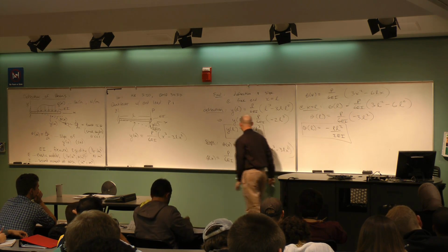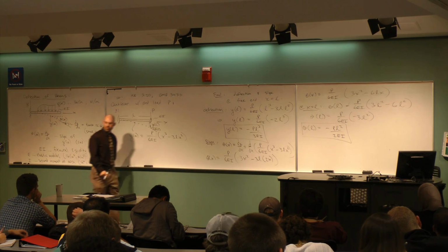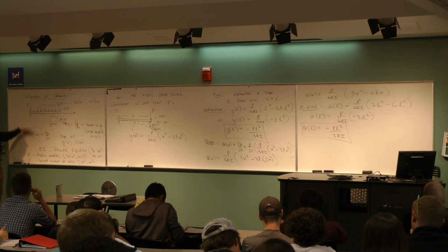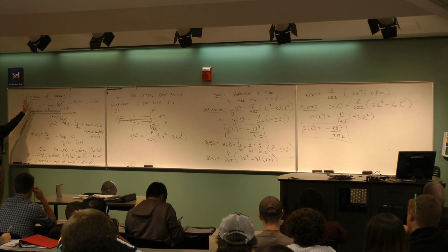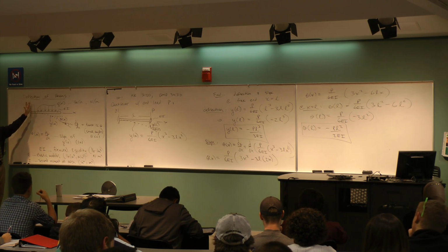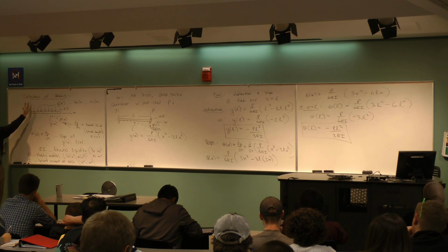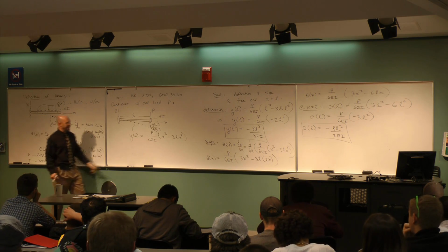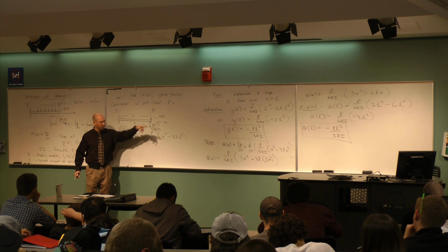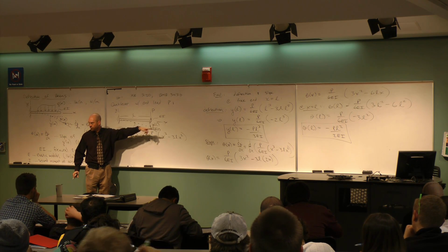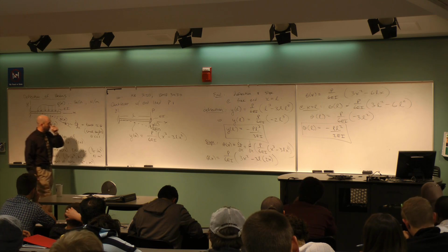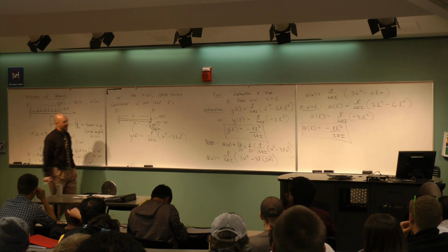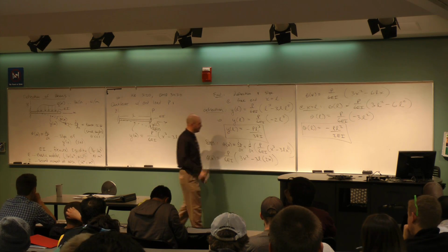Incidentally, why do I have negative numbers for the deflection and the slope here? Yeah, because y is positive up by virtue of how I define this problem. If I had said y was positive down, then the deflection curve would have a negative right here, and these would have been positive numbers. So it's just the way the problem is set up. All right, so the deflection is down, that passes a sanity check. The slope is a negative slope, that passes the sanity check.